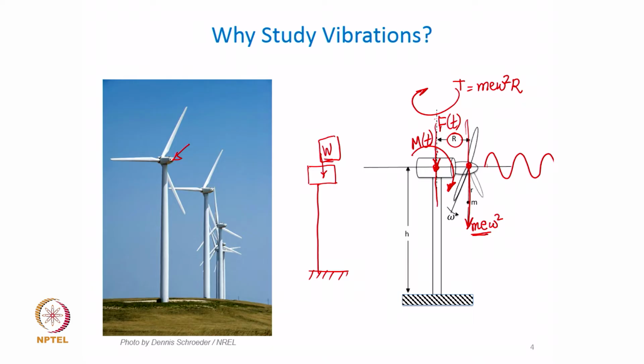All right. And if we now want to look at the stress induced into the column, we would definitely know from our basic strength of material studies that at the root of this column we are going to have maximum stress induced, and we will have to look at all the compressive stresses which are going to be same throughout the cross section because of the compressive force acting, but the bending moment is going to generate a different kind of stress pattern across this line. On this side there will be tensile forces and the compressive stresses will get reinforced because of the bending moment.